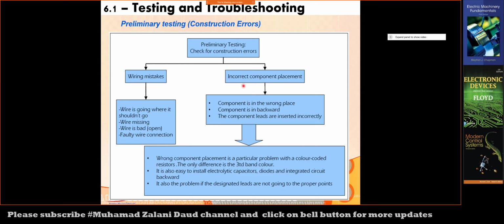Then in terms of component placement, we also have to look closely to check whether the component is placed in the right place. Sometimes a 3-lead component, like a transistor for example, is accidentally placed in the voltage regulator's position, which is also a 3-lead component. Then some components might be placed in a backward direction.